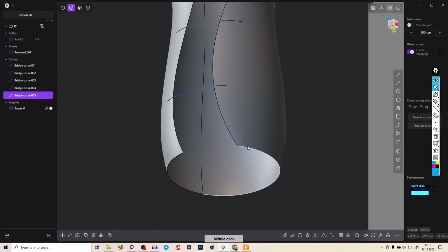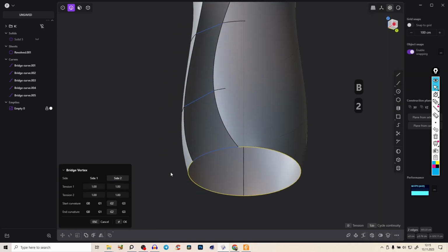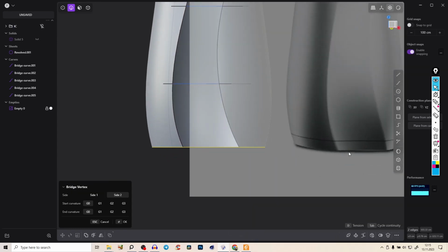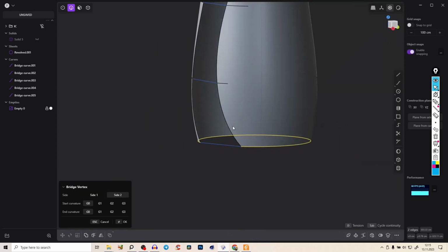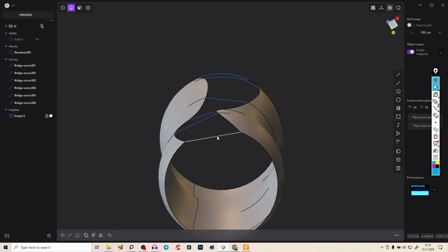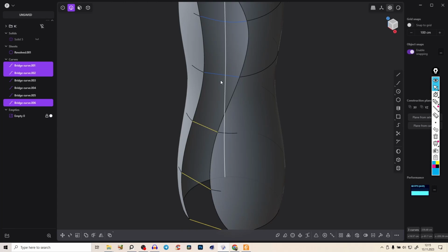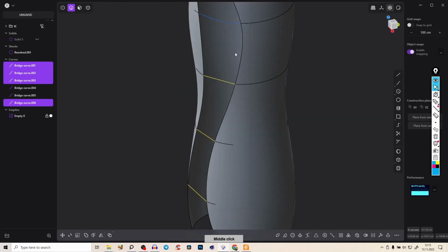And the same here at the bottom. Select both edges, Shift B, just change the sides. And here also G0, because here you see it goes inwards. Perfect. But now you wonder, it doesn't go inwards, it's just straight. That's exactly the point, because now we will select all of those straight lines without those here.